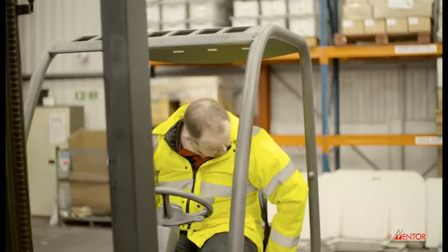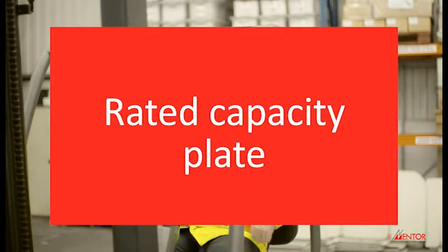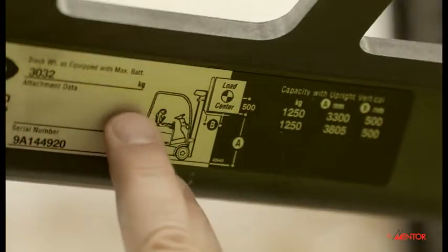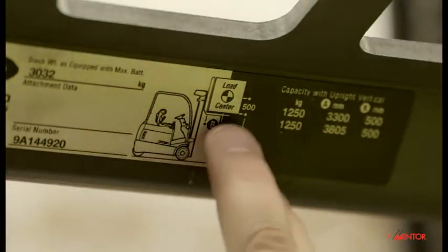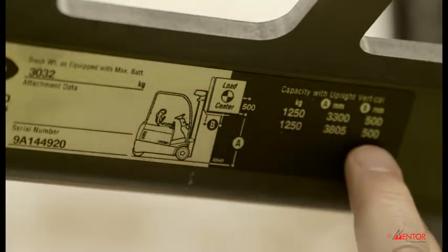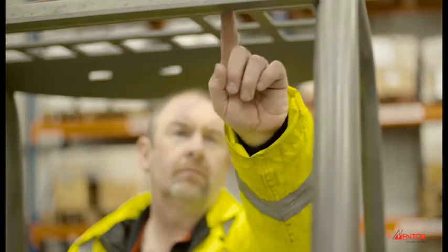Firstly, you should be aware that every lift truck has a rated capacity plate, which details the maximum weight that a machine will safely lift and at what height. It is extremely dangerous for an operator to lift a load that exceeds the capacity of the lift truck. Operators must always be aware of the weight of the loads.